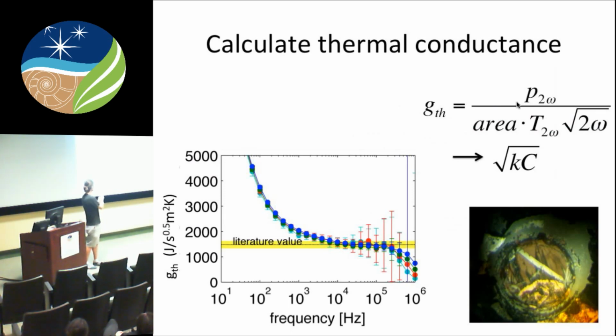So in this case, this ability of the glass to suck heat away from the platinum is telling us the material property of thermal conductivity times heat capacity, and if you like square root, well, okay, it's approaching the square root. That has a name. That's called thermal effusivity. It's the ability of a material to suck heat away from an interface. So that's actually what I measure.